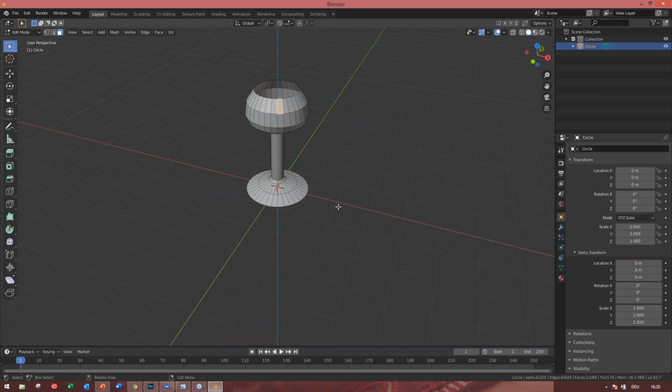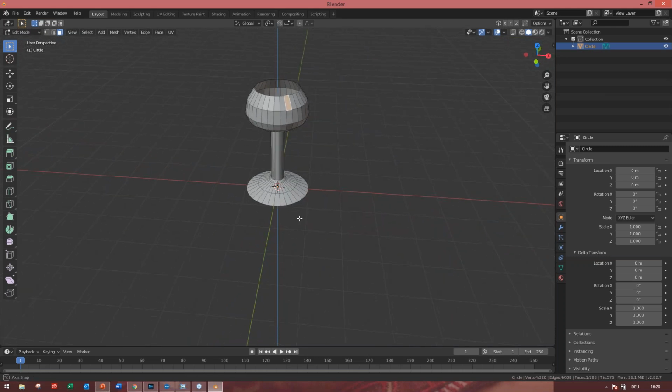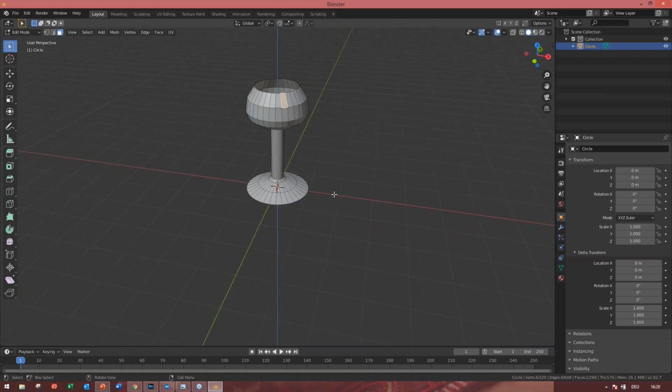If we export this glass now and import it in Pandoras Box, it will be okay. So you can have a 3D object also with quadrant or rectangle faces in Pandoras Box, but you cannot work with this in the Warper. For the Warper, it has to be in triangular faces.